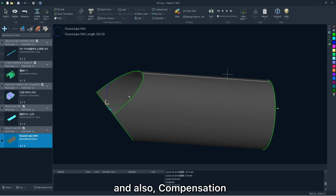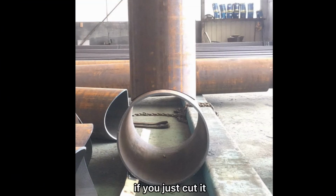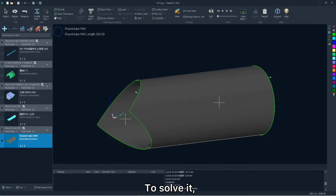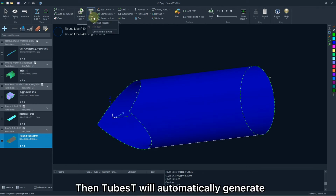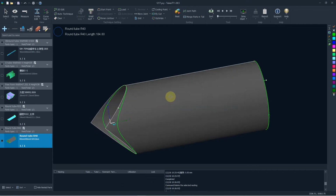And also compensation for special parts to be jointed into a T-shape like this. If you just cut it according to this kind of cutting path, there will be interference due to the differences between the inner and outer contour. To solve it, we can add a weld curve here. Then TubesT will automatically generate a special cutting path to offset the interference.